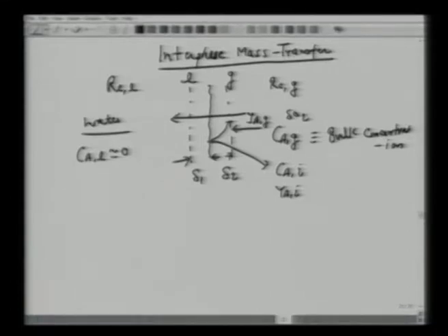Now within the liquid side there will also be concentration gradients. So concentration will also drop from some interface concentration, which we can denote as x_Ai. So x for the liquid phase, y for the gas phase, and then we have again a bulk concentration equivalent to this, C_AL as x_AL. So now we are talking of four concentrations. One in the bulk phase, so that's the concept of a resistance. All resistance is confined to this del 1.